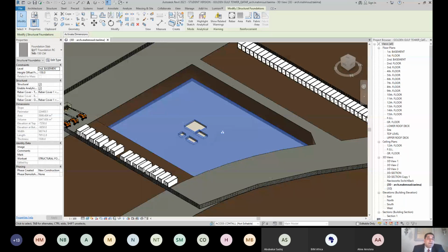In Primavera, we first make a work breakdown structure for the project, consisting of every stage and the activities it has. The first stage is mobilization work, and the next is substructure works, and after that superstructure and facade works, and site finalization.